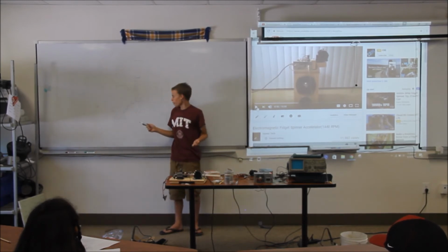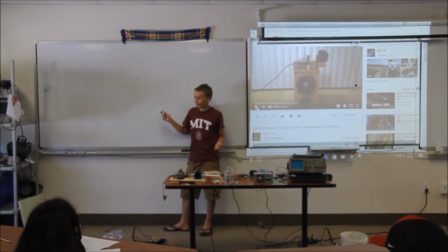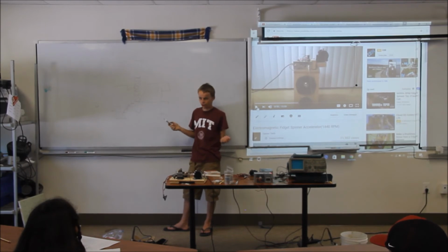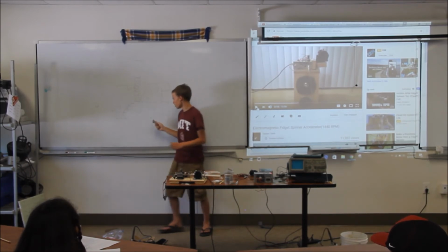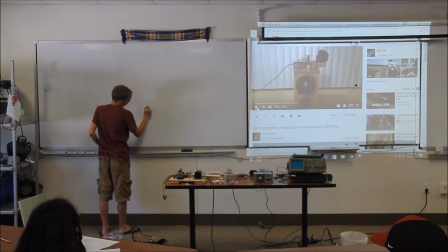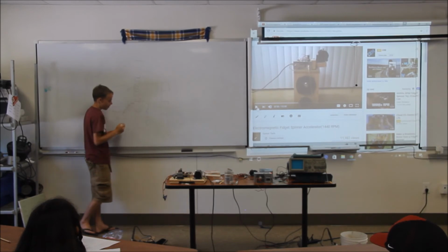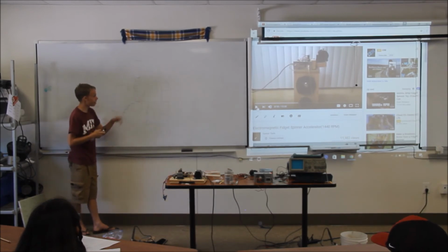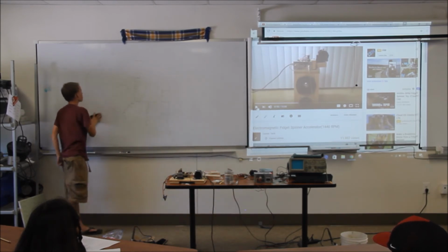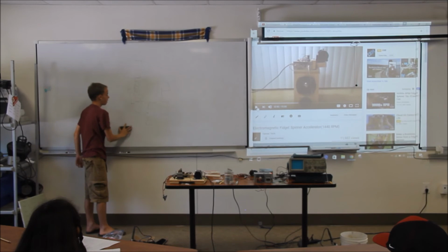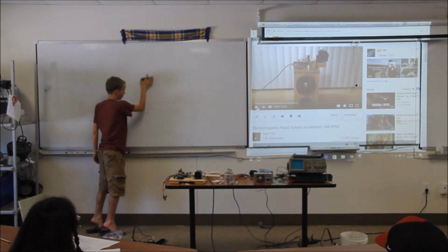Now, I was telling you about that capacitance inside a MOSFET that makes it stay on afterwards. And so you need to put a little resistor on the end of this MOSFET from the gate to ground to discharge that capacitance, so the MOSFET doesn't always stay on and burn up. So that's one circuit that I built. It's pretty cool to understand.